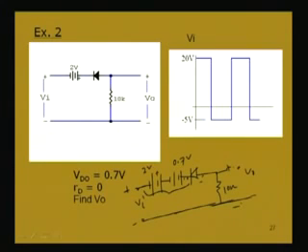So, this is higher at a negative, so this will be reverse biased and will not be conducting. When it does not conduct, the voltage across this resistance will be 0, since no current flows. You have to be careful where you want to find out the voltage. Here it is across this resistance.